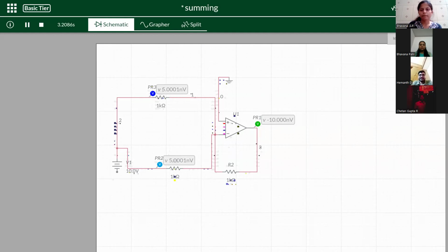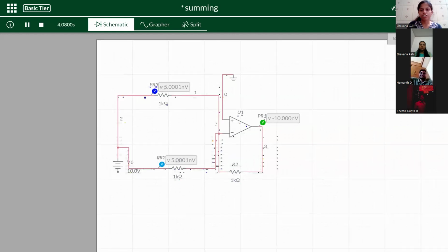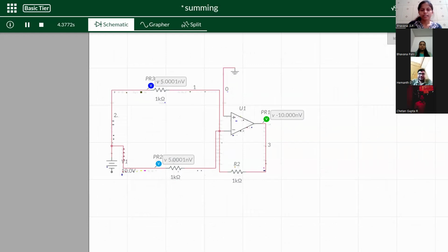The circuit in the image features an operational amplifier arranged with equal resistor values in a classic differential configuration. Abstract. This simulated circuit demonstrates a differential amplifier using an ideal op-amp and precision resistors. The input side receives a 10-volt source divided equally between two nodes through two 1 kilo ohm resistors, thus presenting identical voltages, 5 volts, to both the inverting and non-inverting terminals of the op-amp.